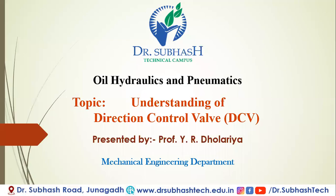Hello, today we are going to study the direction control valve. In a hydraulic circuit, the most useful component is the direction control valve, where the fluid flow path is different every time. Not every component and circuit works on the same path with a continuous flow in a hydraulic system. So it's necessary to use a direction control valve to give the flow direction of the hydraulic circuit to the different components and working parts.